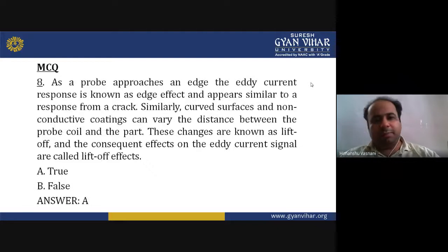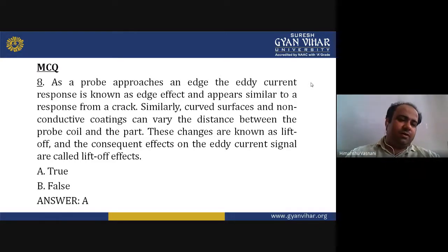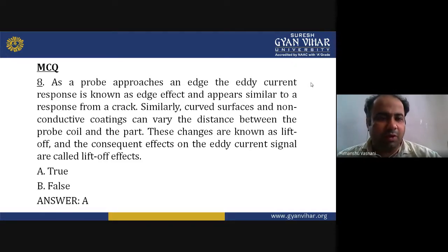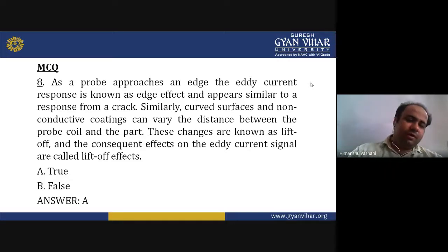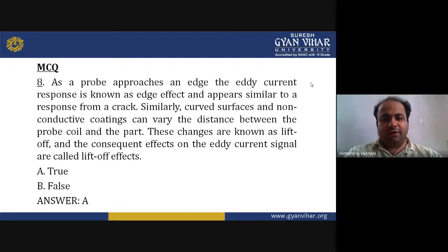As the probe approaches an edge, the eddy current response is known as edge effect and appears similar to a response from a crack. Similarly, curved surface and non-conductive coatings vary with the distance between the probe coil and the part. These changes are known as lift off and the consequent effects on the eddy current signal are called lift off effects. So is it true or false? It's true. The lift off effects is true. Answer is A.